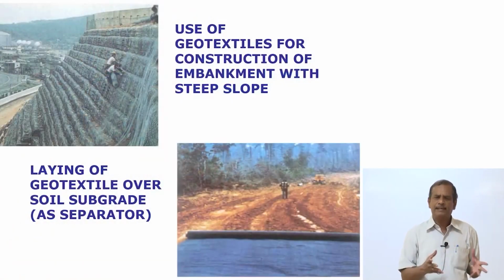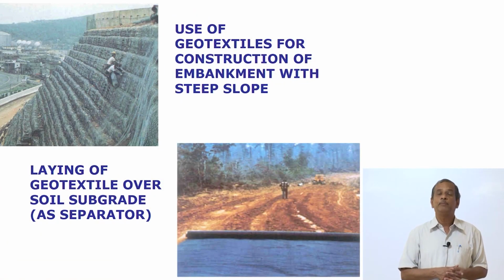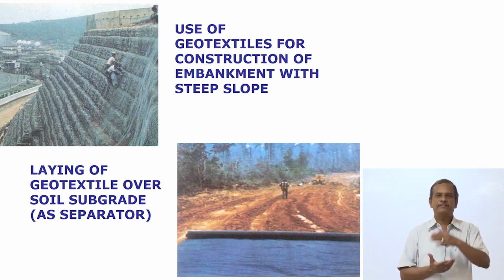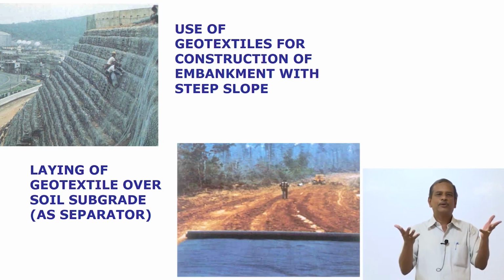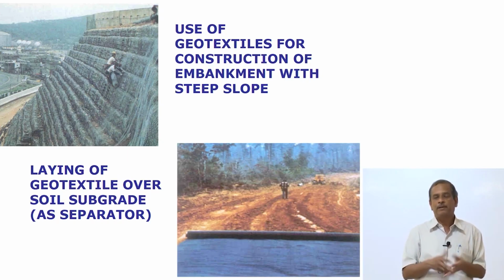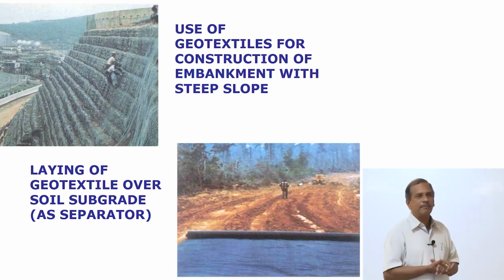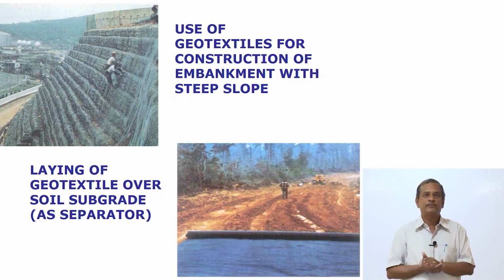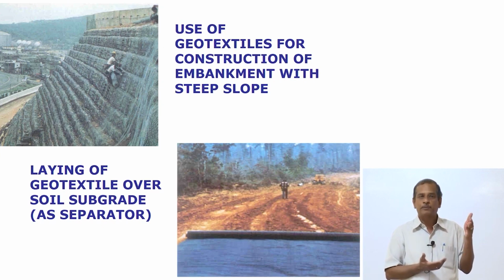Again, we have got better materials. I think it's time that we use new materials. One new material that can be used is geotextiles. I think after the recent floods last year, many of the roads in Kerala were cut off because of landslides. So, what should I do now? These geotextiles can be used for embankments with steep slopes to ensure better slope stability.